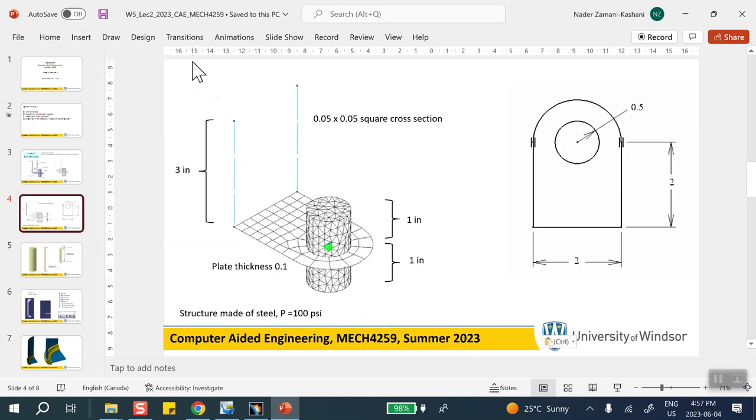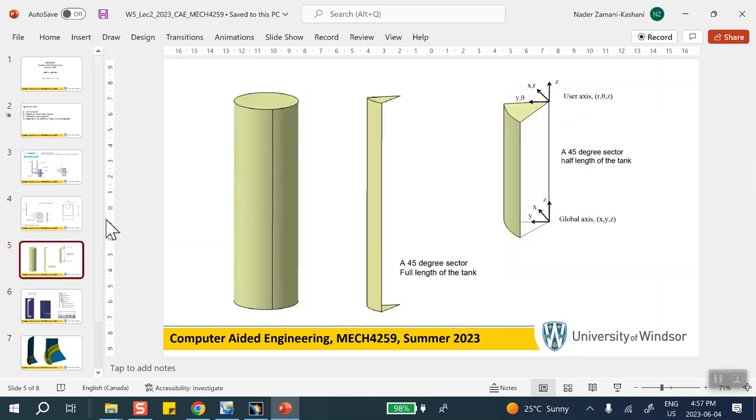Now, we'll come to this in a minute. I want to show you why it is important actually to do hybrid analysis. Why do we have to use mixed elements? For example, do you remember this problem is a thin wall pressure vessel, or a pressure vessel in general? Now, at the seam, there's a lot of crazy things that can go on because these are where the bulk of the stress is. And if we do it with shell element, unless we take a very, very, very fine mesh around these circles, the results are not very reliable.